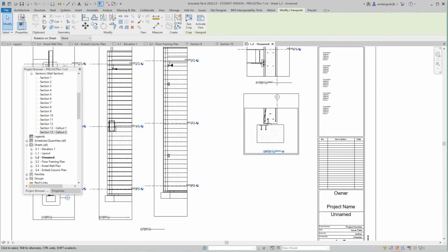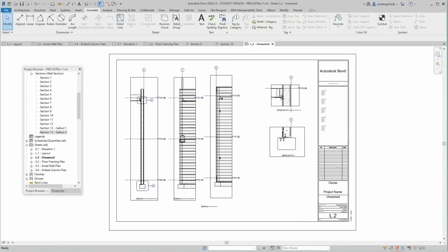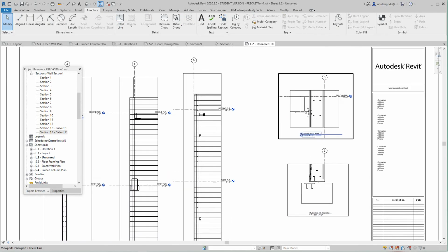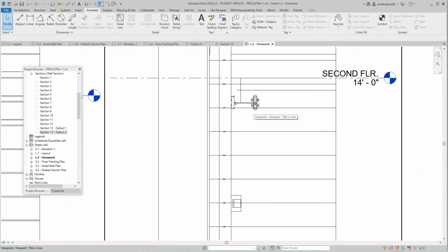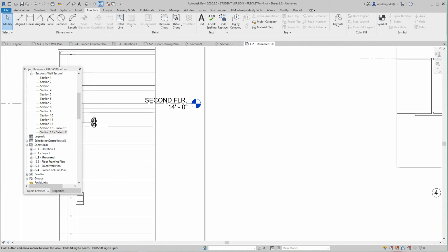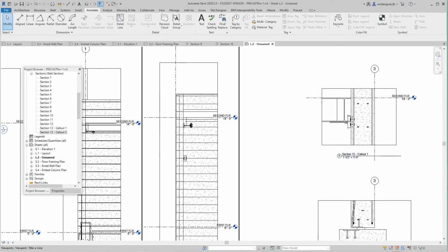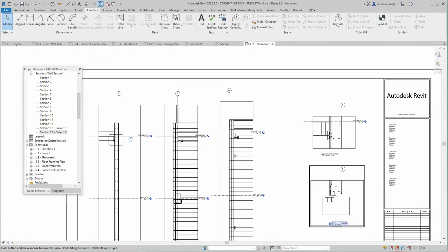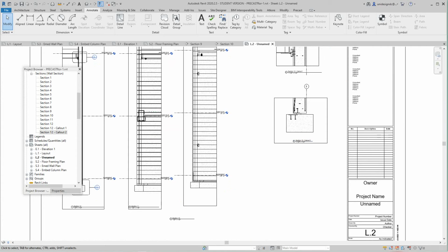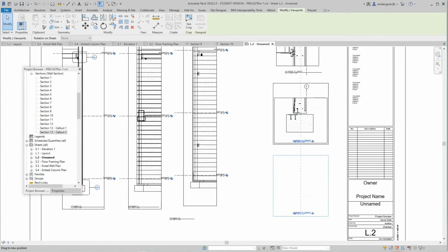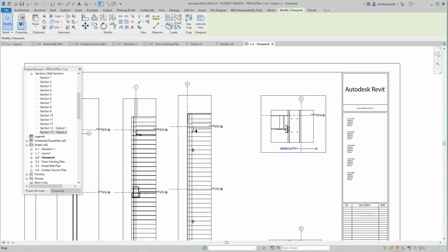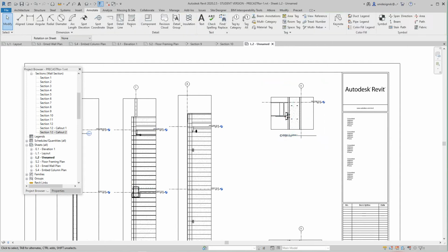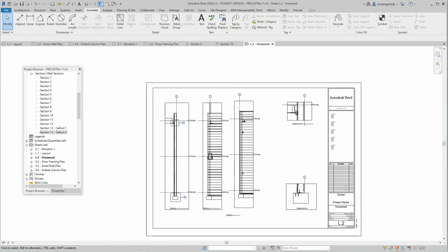You guys get the idea of what's happening here and what you need to do. I'm going to detail, so go in and add these dimensions. You can dimension things over here. Now here's another PSA that we might want to pull off because it's in a different area. So let's just go here. Let's put this down since it's at the bottom. And then we'll go with these at the top for this sheet. So this is another sheet in our erection drawings. They're the sections and details.